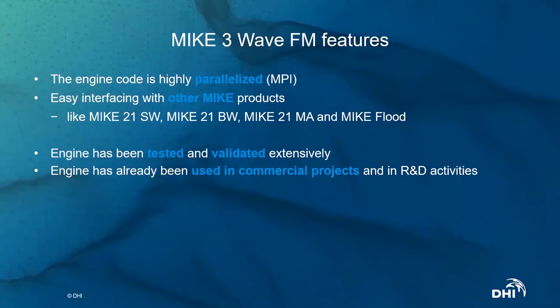We have tested the MPI parallelization, which I will also show in a second, on 320 cores, which has shown a superlinear performance, where we have a fit into a faster pass of the memory, as this really helps speed up the computational time. And the MIKE 3 Wave FM model has already been tested and validated quite extensively during the development phase, and also through activities in commercial projects and in research and development activities.